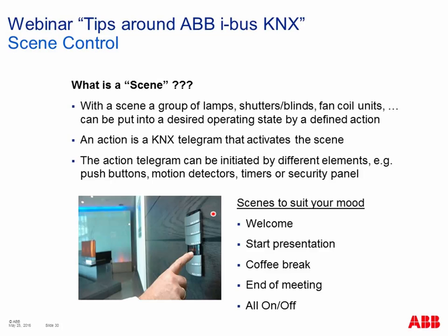Such scenes can be used, like here, in a meeting or in a training room as a welcome scene. So now the trainer goes in the room, unlocks the door, opens the door, and starts a kind of welcome scene. All lights go on, the fan coil unit goes into comfort mode, the shutter or the blinds drive to the up position, and the music goes on and plays some sounds. And now when he starts the presentation, he presses again the next button on the next side of the rocker to start the presentation scene.